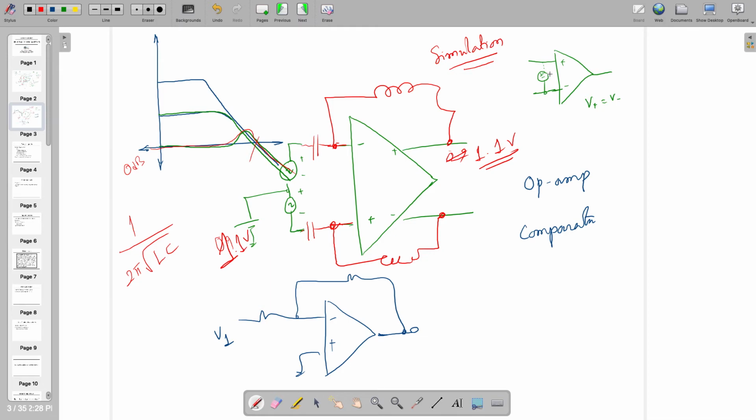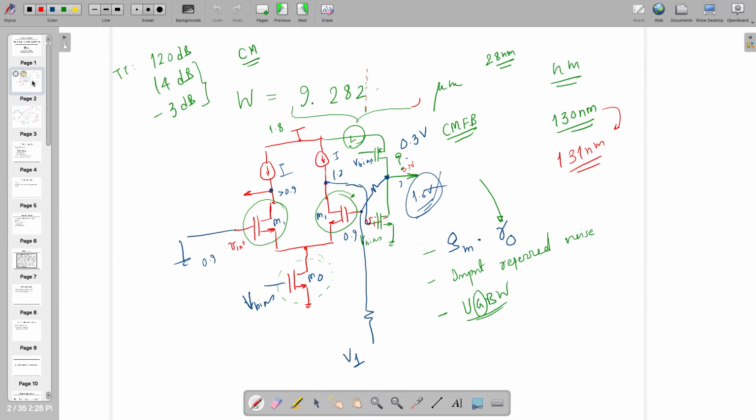Right? So this is how it goes, and that is how I explained to you that whenever there is an op-amp which is not kept in feedback, then you don't worry about common mode feedback. Right? It's an open loop. But if it is in feedback, and if you are going to connect a single stage, you don't need common mode feedback. If you have two stages, you need common mode feedback. For an odd number of stages, CMFB is not required. For an even number of stages, CMFB is required. So this is the reality, because in between the stages, you don't know what is happening. So for such a case, common mode feedback will be needed for sure, because it's two stages. For the case of only one odd stage, are you following what I mean?